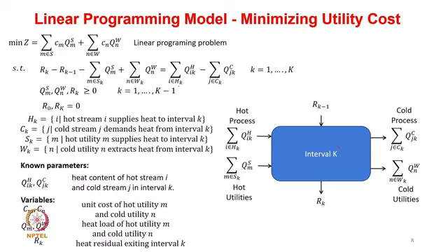So the signs got changed, therefore it is Q_hik minus Q_cgk, and we have put summation here and there everywhere, because there could be multiple such streams. If there are multiple hot streams and hot utilities, cold streams and cold utilities, you lump them together by means of the summation and write the balance, and you have such capital K intervals.